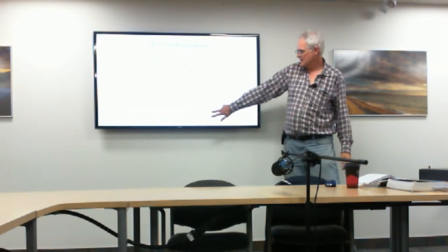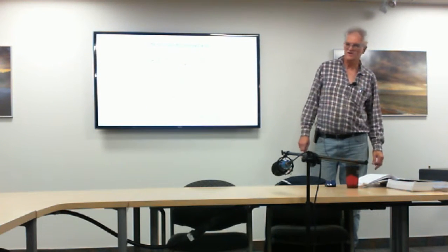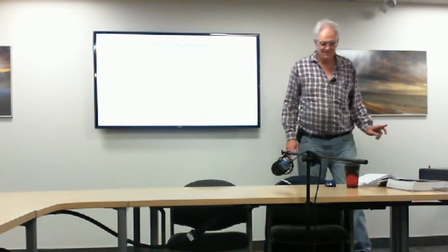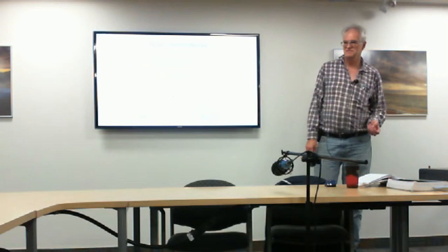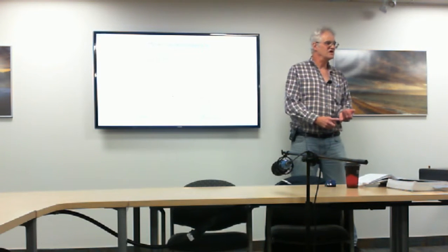It's going to affect the beat frequency oscillator, because for a CW signal it has to be offset by about 800 hertz. But at the other extreme, for our single sideband signal, we have suppressed carrier, so now we have no carrier, nothing to measure against to recover our signal.